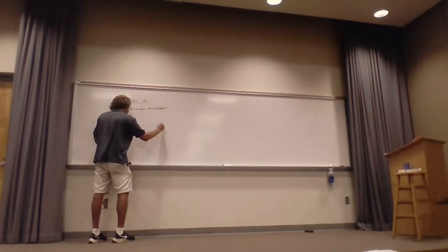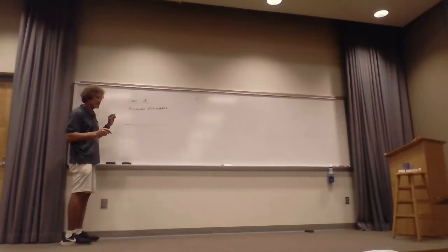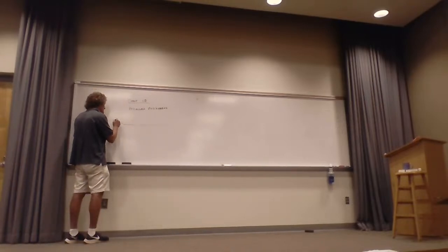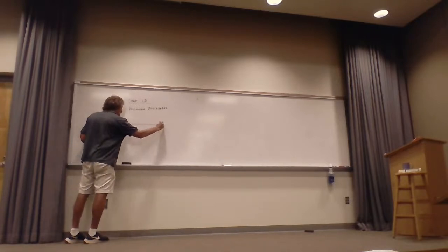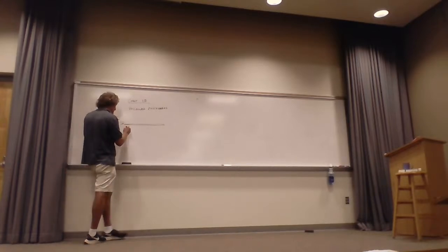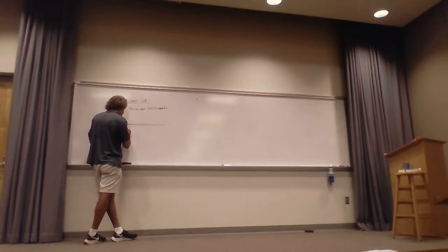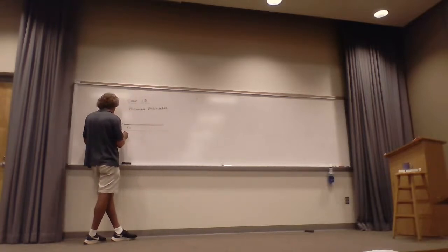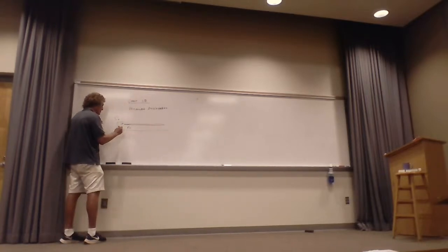What you're normally talking about is a board that has a copper top. So it's got a thin layer of copper clad, they call it, right here. And then they have a dielectric material with some epsilon relative here. And then they have another piece of copper. So you've got copper on top and copper here.